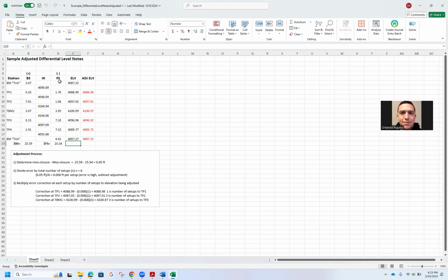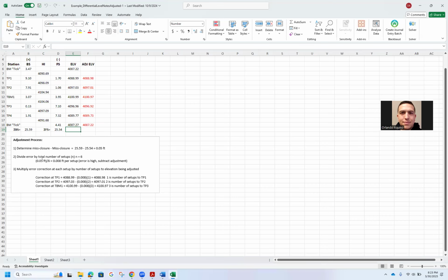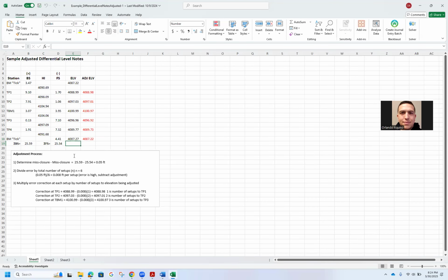Well, let me double check everything. I'll add up all my foresights and all my backsights, and the deltas of my foresights and backsights should be the same as my starting and closing elevation, right? So we did that, and we get 5 hundredths. So we are checking, right? My deltas between my foresights and backsights and my starting and ending are exactly the same at 5 hundredths. So now what do I have to do to make the adjusted elevation work?